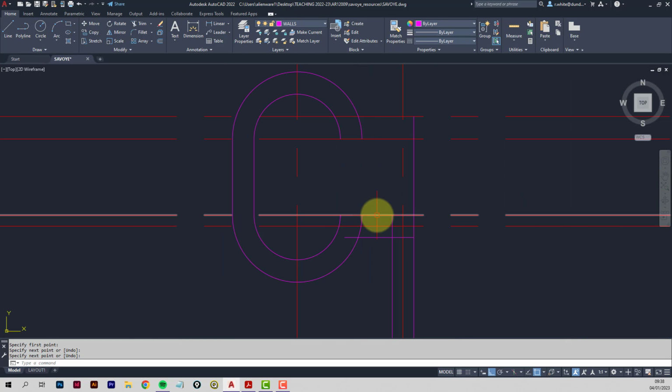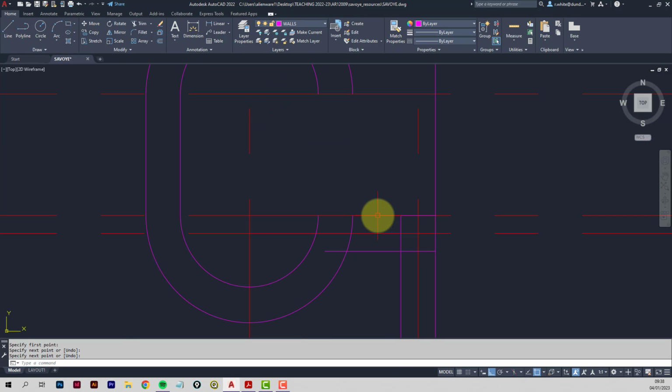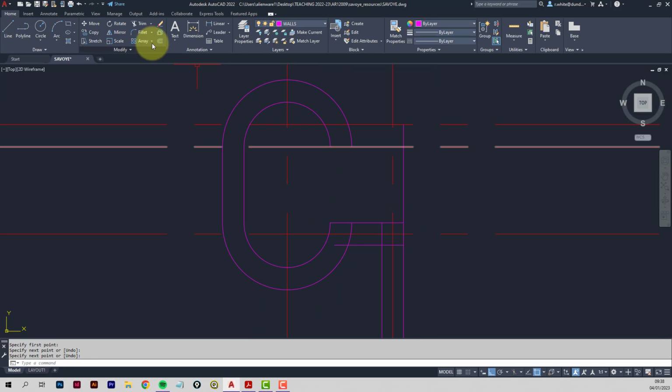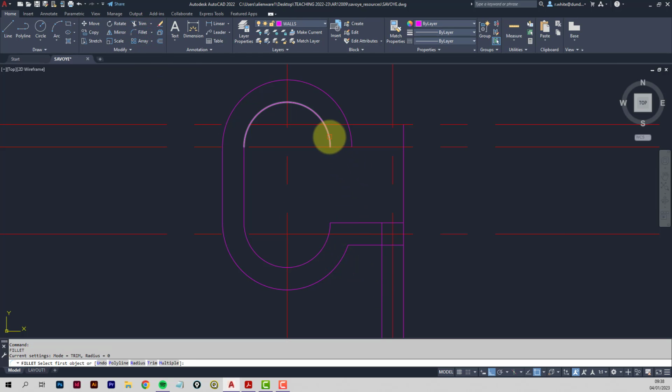Okay, this grid line is a little bit extensive, it's going to be a little bit difficult to edit, so I am actually going to delete that one and just draw a line in its place. Okay, the rest of the work should be fillets. So a fillet, join these two, enter, join these two, enter, join these two, and then we've just got the wall end to create,